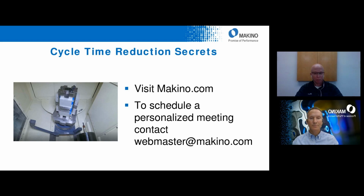I need to confirm that. But positional moves, no, you have to be at the pallet, the second reference position, basically the safe location with the spindle or tool before your pallet change. But I'm pretty sure you can do a tool change with a pallet change. But again, I'll follow up. We can do a follow up and confirm that.